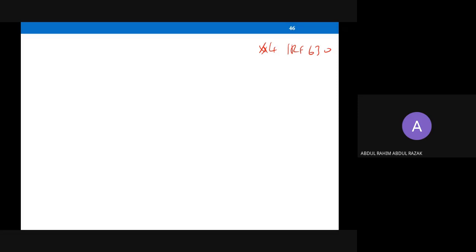Maybe you want a compact package, so you may buy the SMD parts, surface mount type. Or if you have a larger space to put more parts, you can opt for a TO220AB. Maybe you can put a bigger heatsink, so you can push in more current. So over here we have a dashboard which shows us that this device can go up to 9.3 ampere. But it's not like that.